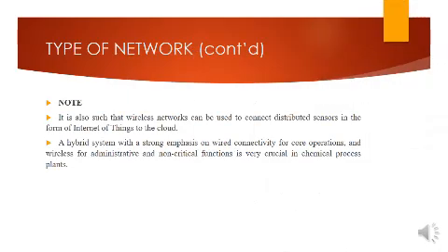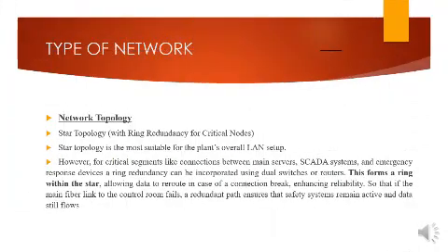We also use Internet of Things to upload all the necessary information to the cloud, along with real-time information, to make sure that we have access and can use it to improve the efficiency of the chemical plant. Then we have the network topology, where we use the ring topology to make sure that even if one of the fiber links breaks, it doesn't affect every unit within the plant, but the data still continually flows and is consistent.